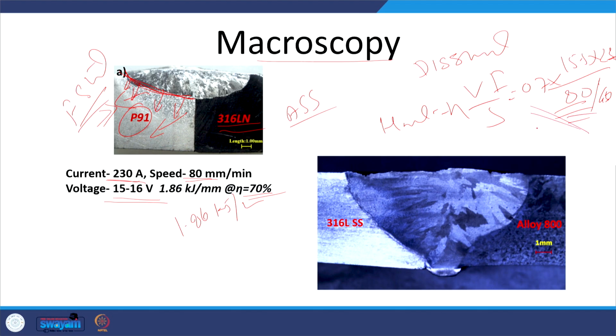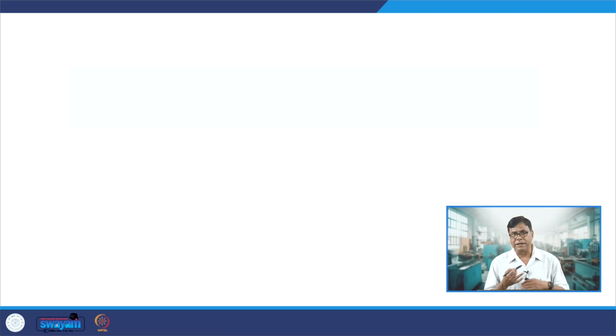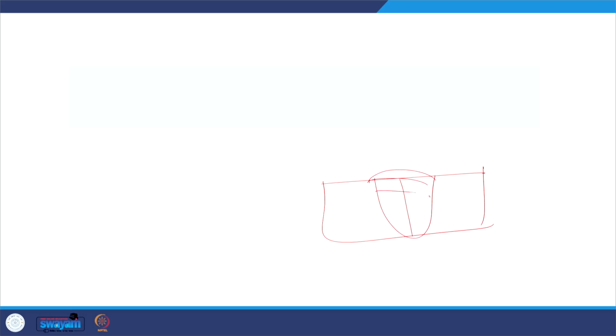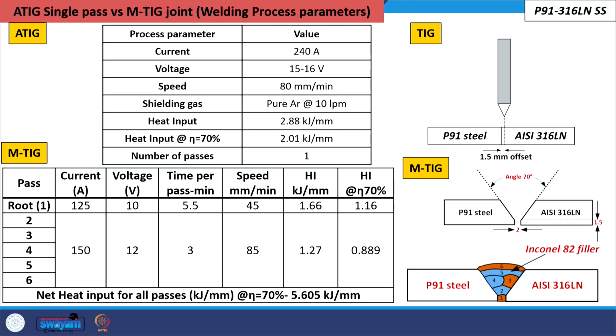So, this is what will be giving us the net heat input. Then we will see how to characterize the weld bead geometry. When the weld joint is developed like this, it produces various geometrical features. So it is important that low magnification images of the weld joint are captured, and for that we need to use the stereoscope. In this particular case study, we have used activated fluxes with